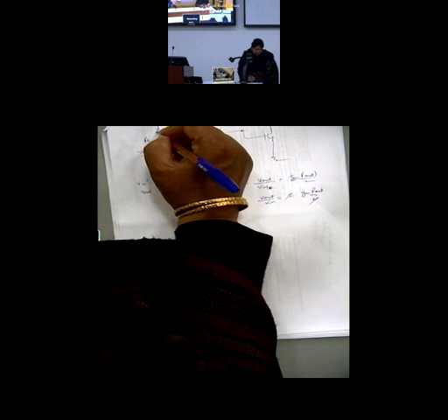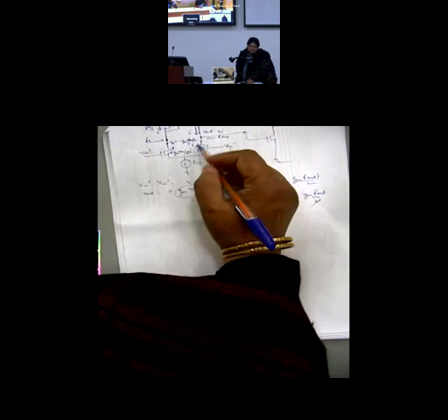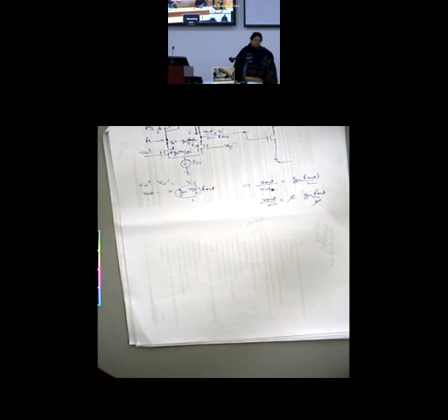So what is happening is that a current I flows through this, because they are in series, this also has to carry a current I. This also has to carry a current I because they are mirrored. If this is M3 and M4, both PMOSes, they should be matched, so this must also carry a current I. So this I and this I, together they will come out of this node by KCL, and will cause a drop across R out.